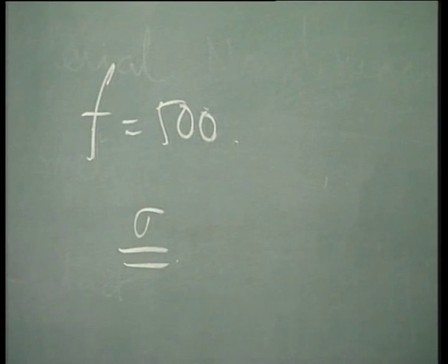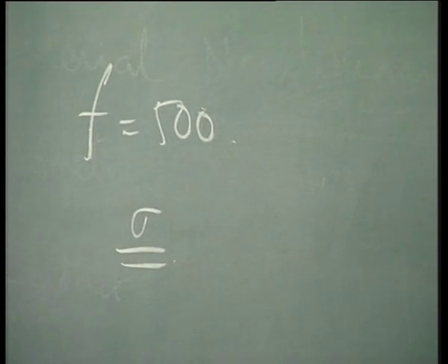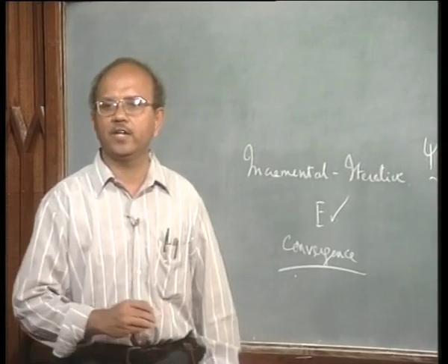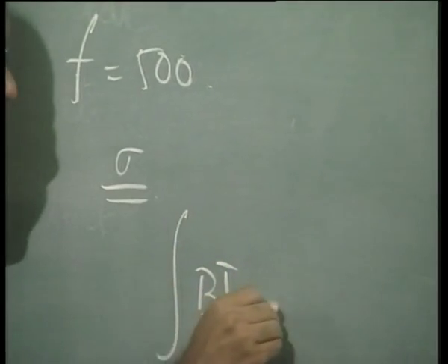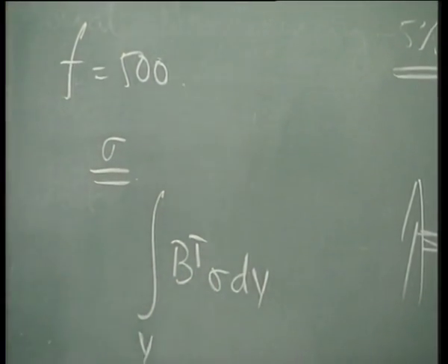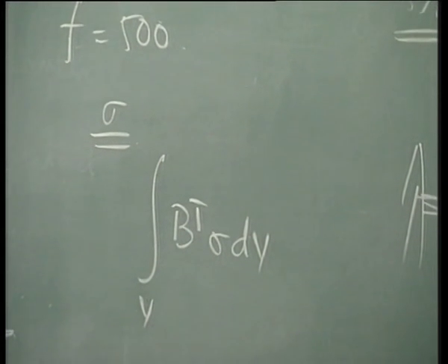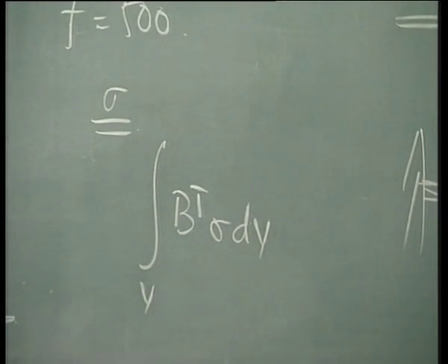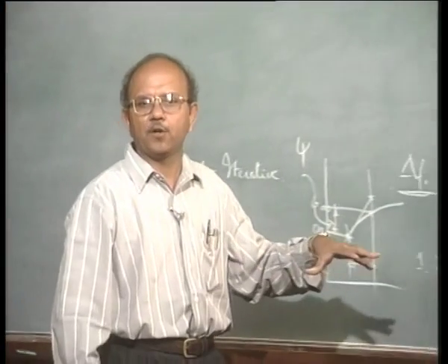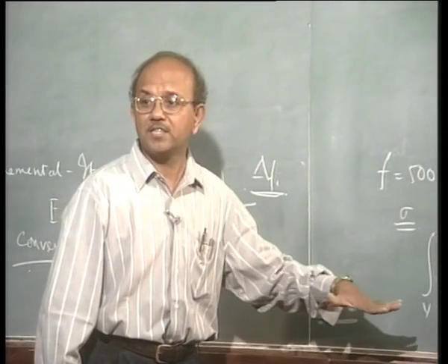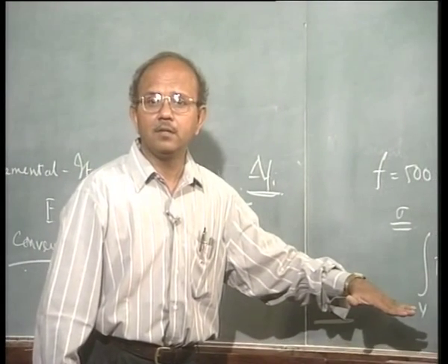You can easily see, for example, in a finite element situation, the internal forces are given by integral B transpose sigma dV. You can very easily see that is the force. We will derive that in the next class. Let us first understand the conceptual aspect. So that is the force, right?